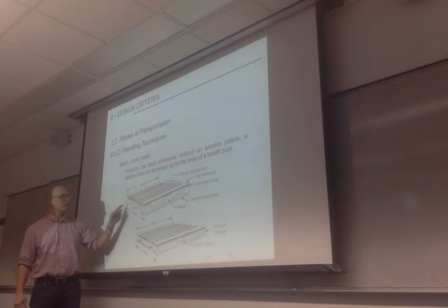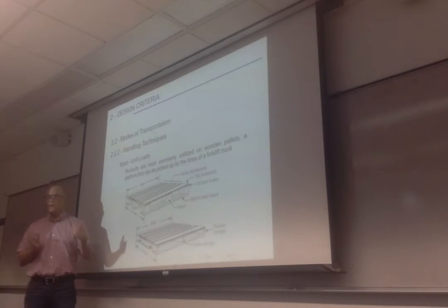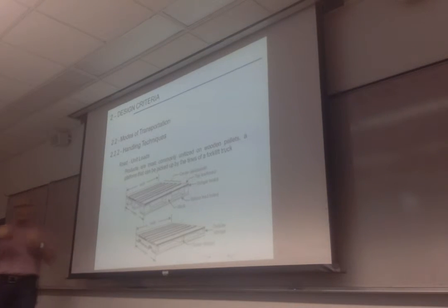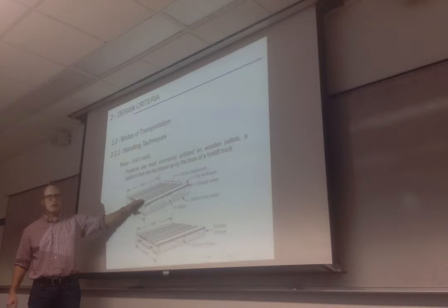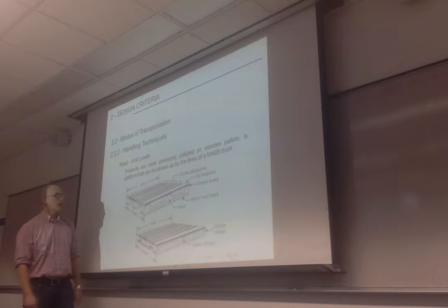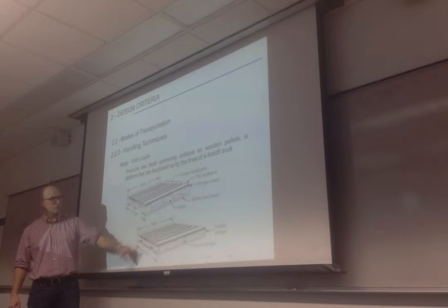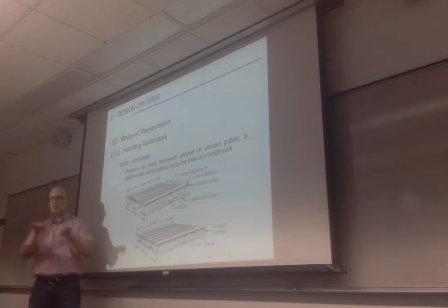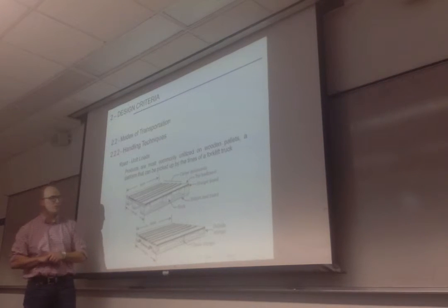One of the advantages of the block pallet is that it can be easily forkliftable in 4 directions, because those pallets sometimes have to be turned to be loaded, and so on. You can have a pallet with one deck, or a double deck that can be flipped for any reason, which might be a lot more sturdy as well. Stringer pallets are a little bit more sturdy. They may have some openings on the side to be able to slide and move, but they are not necessarily designed to be handled in 4 directions. Typically, it would be 2 directions.